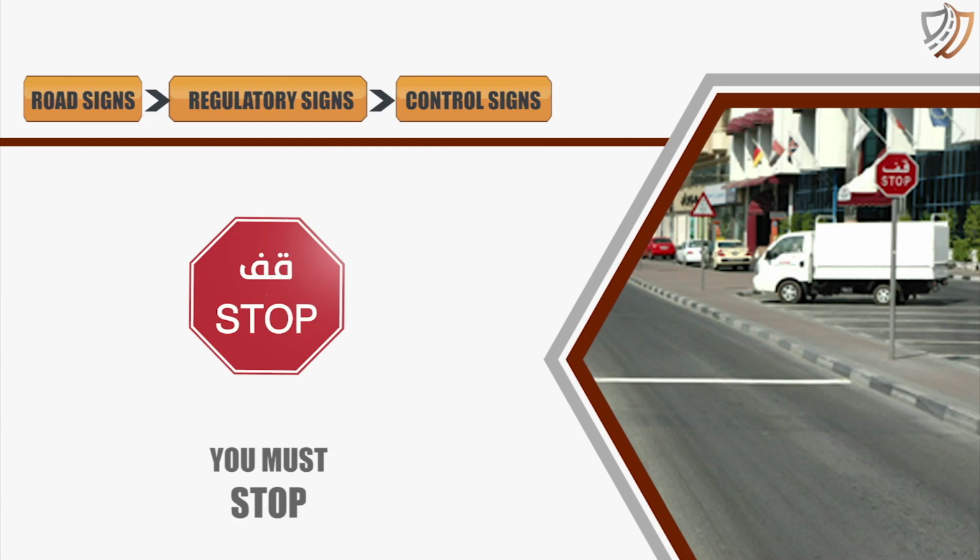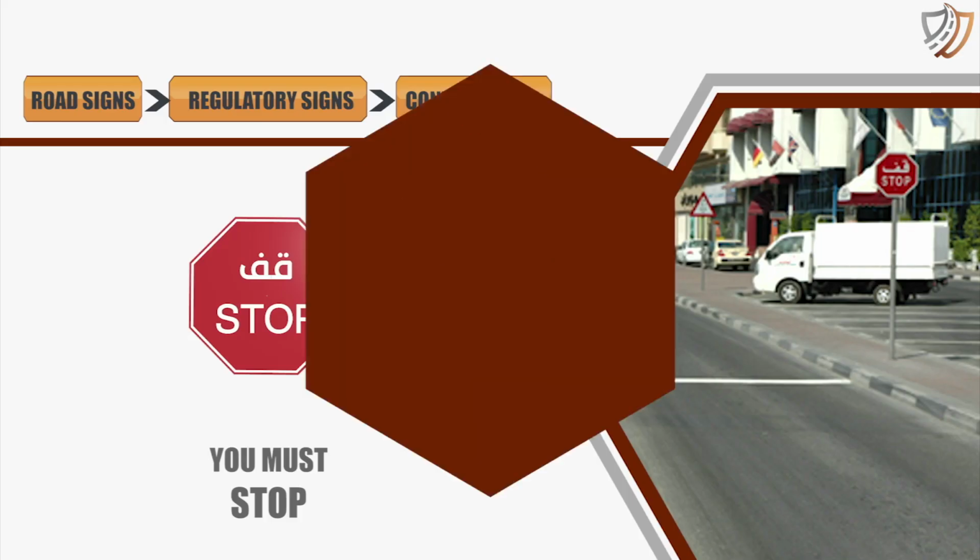Stop sign. This sign means motorist must stop. It is the only sign in the signing system which has the unique octagonal shape to differentiate from other signs because of its importance. This sign is usually found in the area where the driver's view might be obstructed or where there is an actual or hidden hazard, such as at T-junctions, service roads, slip lanes, side roads, U-turns, and exit points. This sign instructs that drivers must stop before the stop line, even if there is no traffic, scan the road, and then proceed safely.